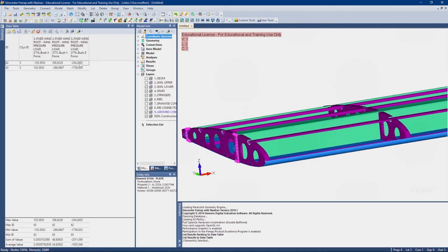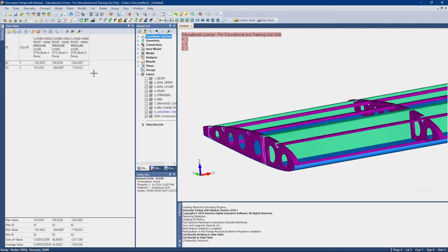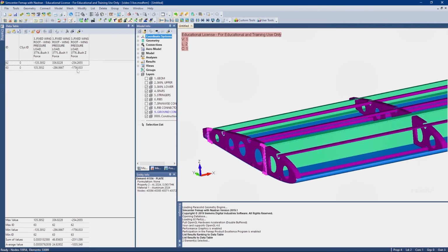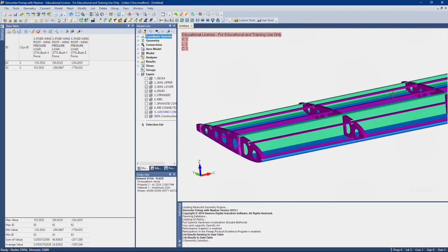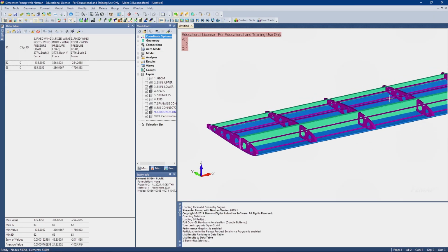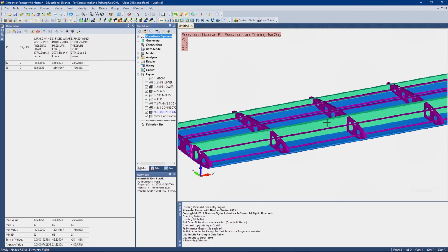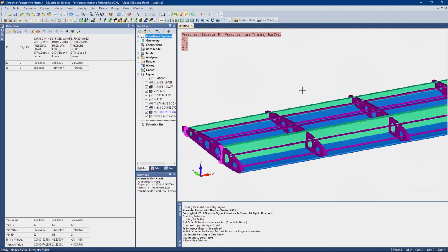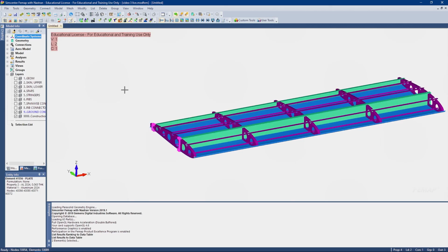And we have negative 250 on the rear one, and negative 1750 on the front one, and summing that gives us 2,000 pounds. So we were more or less on the money as far as getting roughly 2,000 pounds of lift on this wing. So the cool thing about these data tables is, let me just show you guys real quick.